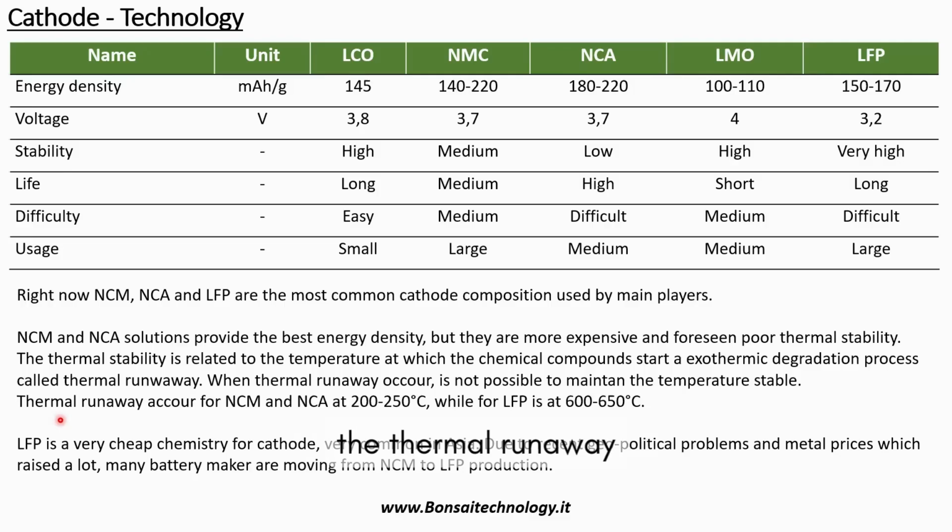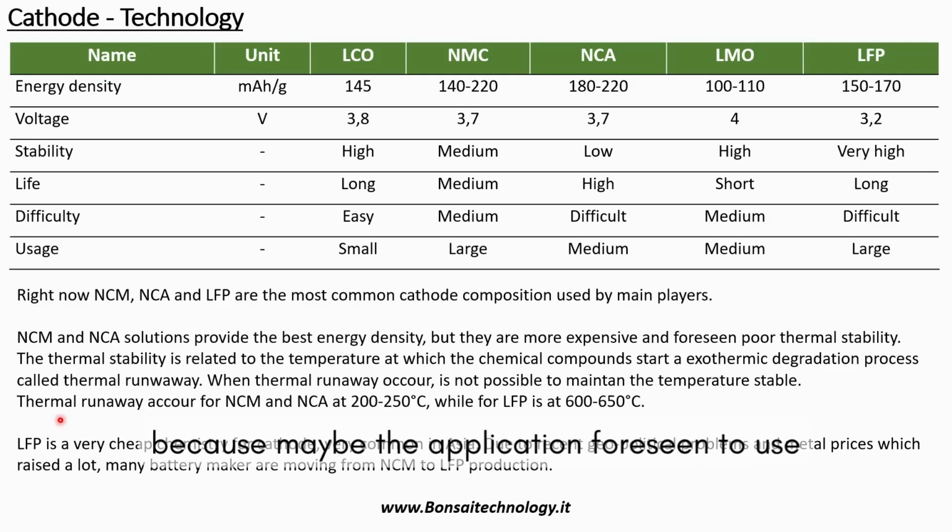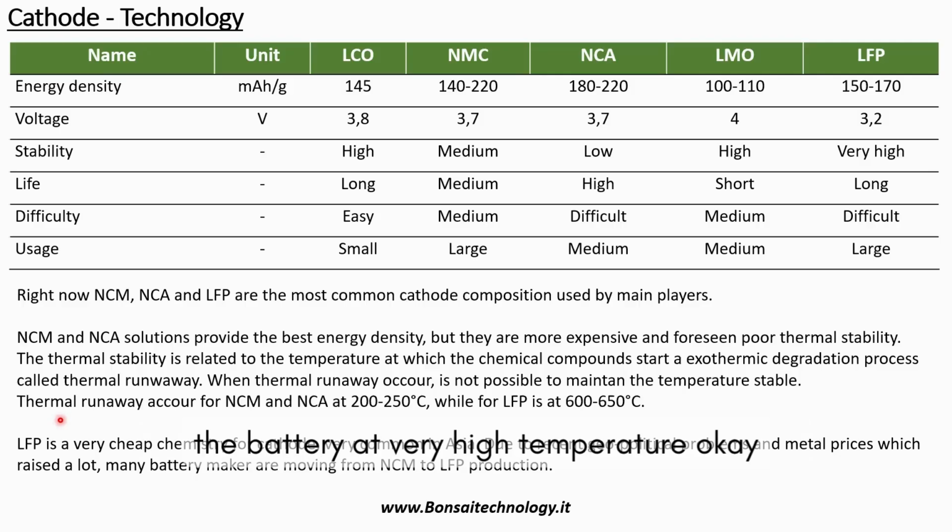Thermal runaway occurs for NMC at about 200 degrees, but for LFP this temperature is very, very high. That means that LFP is able to survive even in very extreme conditions. Indeed, in some areas worldwide, it's preferred to use LFP rather than NMC because the application may foresee using the battery at very high temperature, and this is not possible for NMC, for example.